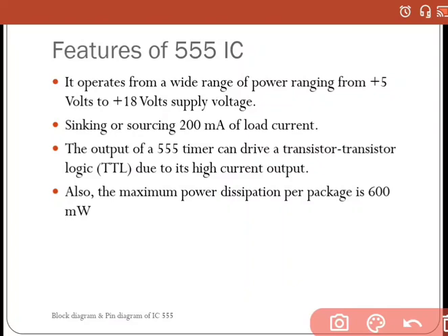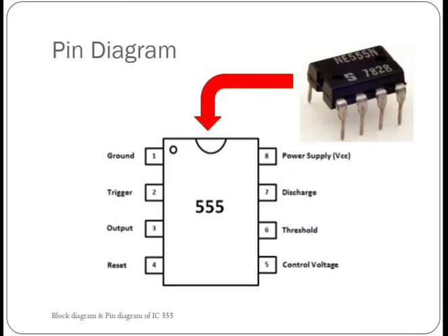It is 200 milliampere, and it can drive a load whose maximum load current is 200 milliampere. And because of this high current value, it can drive TTL, that is transistor-transistor logic devices. It has a maximum power dissipation of 600 milliwatt. Now we go to the next slide.